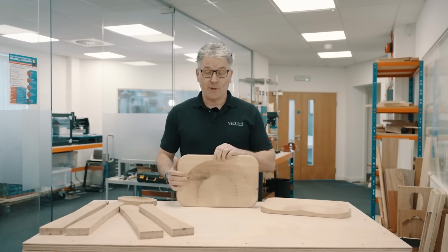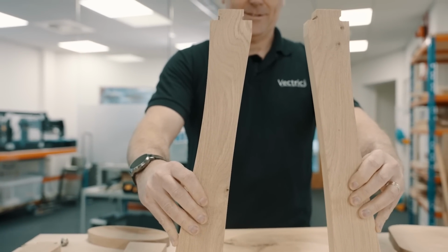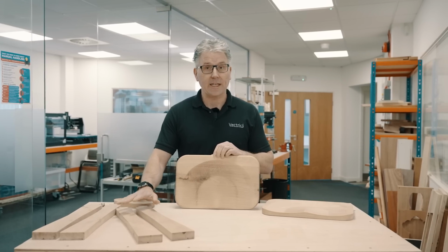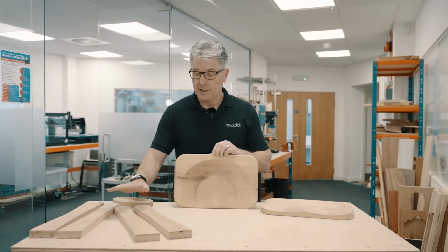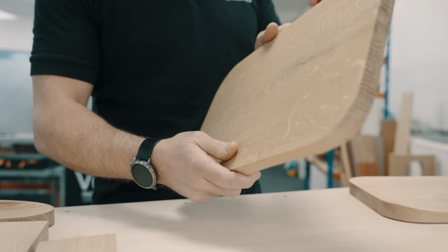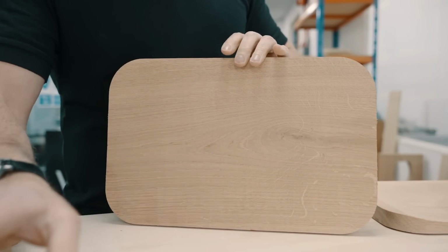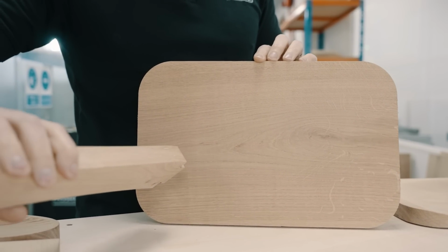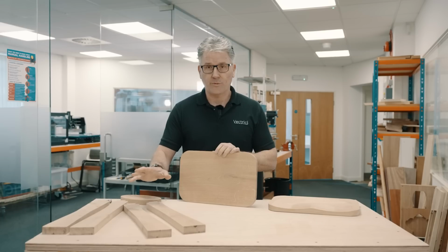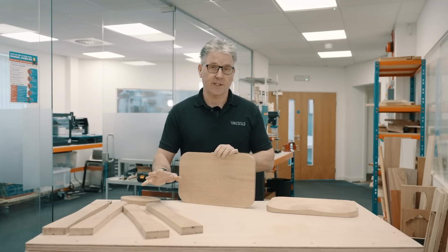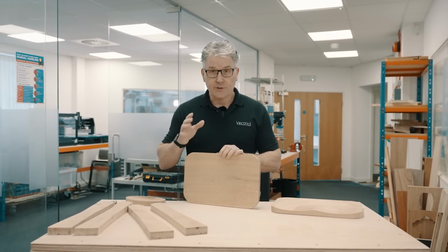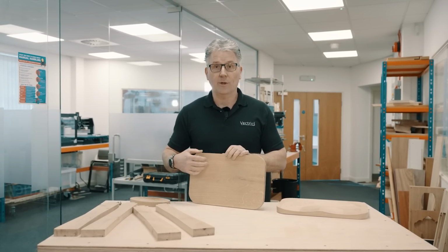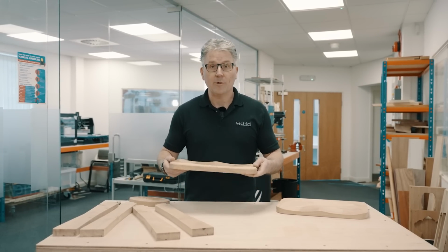Obviously, it's not much of a stool without legs, so I've already pre-cut some legs. Not to worry, the sheets are in the files that you're going to get with this project, so you can cut your own legs, and a back plate also that we're going to attach to the bottom of this particular seat so that I have locations to glue the legs into. I'm not going to go over how I made those. It's pretty easy stuff, a few profile cuts and some pockets, and you can figure that out in the file. So right now I'm going to run back over to the CNC machine, cut out the plate, do a little glue up and assembly, and this will be almost ready to go.